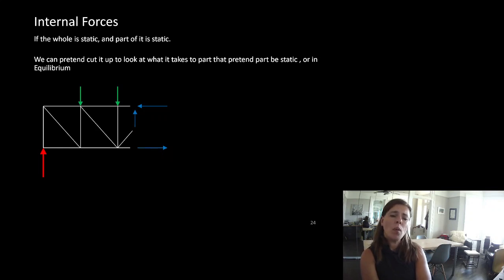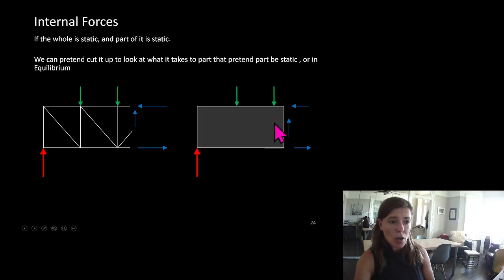What do we know about equal and opposite forces? They can be written as a moment. So if we wanted to take the compression in the top chord and the tension in the bottom chord, if they were equal and opposite, and write it as a moment, if we were talking about a beam and this is what it looked like, instead of looking at a top chord and a bottom chord, we could write that as a moment.